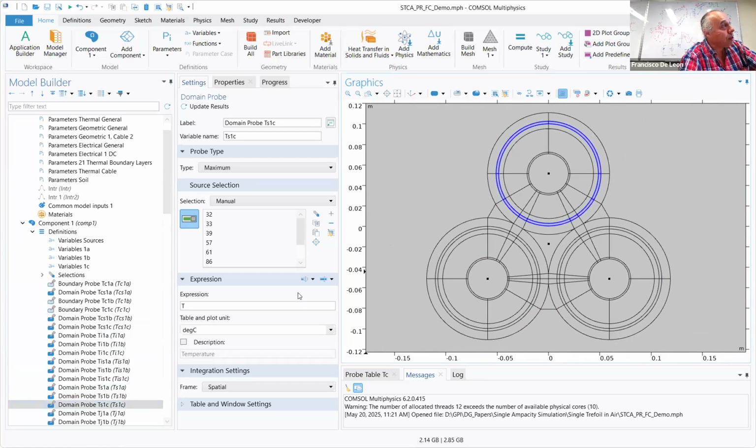So the condition is the same for, let's say, a large power transformer. You still need to put the thermal insulation limit, the maximum temperature at which your insulation performs, in the conductor, let's say 90 degrees. If you're using a class F transformer, I think that has the 90 degrees operation temperature at the conductor. So these things are the same. If it is a cable or a transformer, these things can be extrapolated easily.